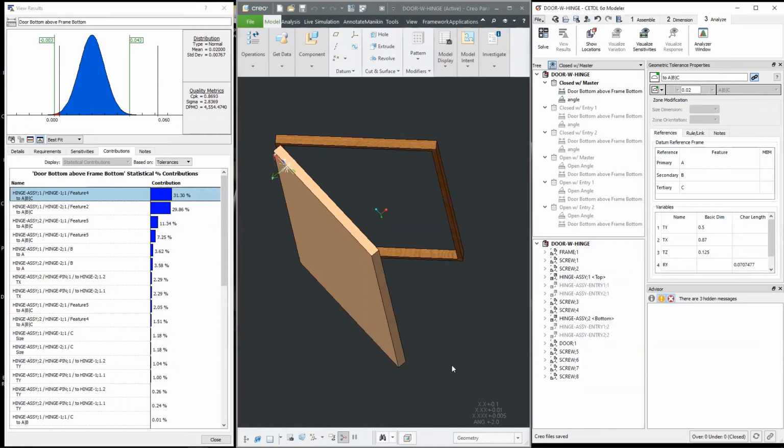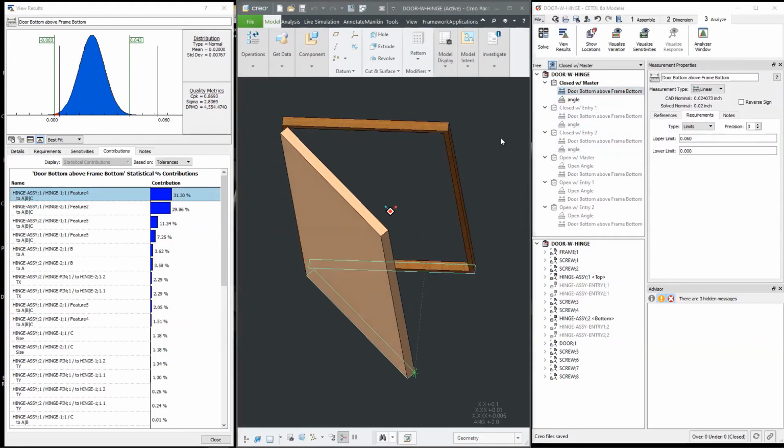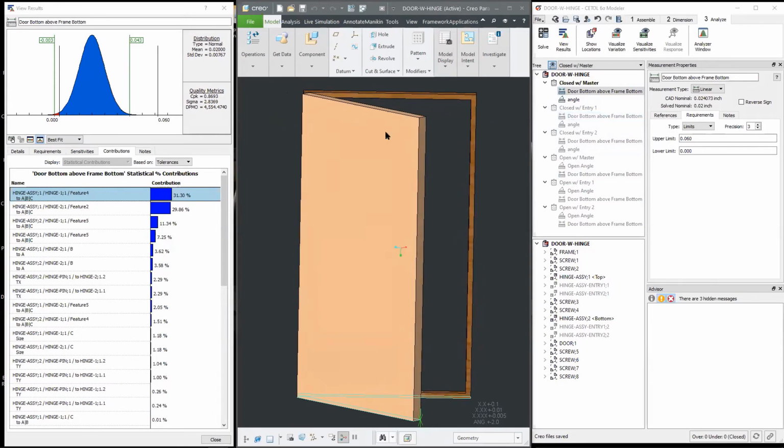All right. So we have, again, these are the different results with the different entries. So comparing the clearance with the bottom of the door between what we had proposed, and clearly even what we had proposed needs a little bit of work, right? We're probably going to want to tweak this either by reducing the width of this or moving it to the right so that we get more of the units above our lower threshold.